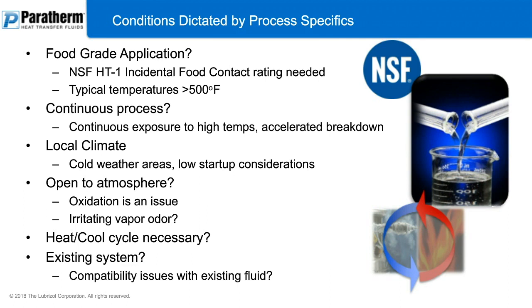There's a slight but obvious and key difference between the more common H1 designation for lubricant oils and the HT1, which is specific to heat transfer fluids. And that's an important designation that you should not confuse. We've seen some folks that are using a fluid with an H1 designation, and what you should be concerned about is that maybe someone sold you a lubricating oil instead of a heat transfer fluid for your system, and there's a key difference between that.